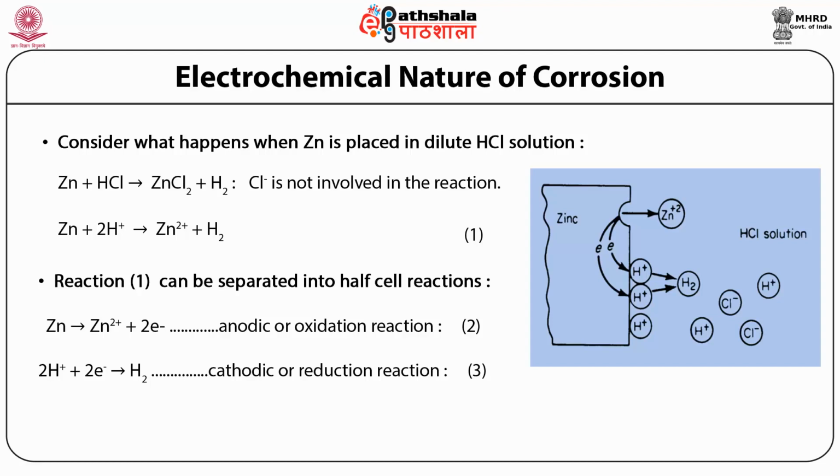If anywhere in a material an electron acceptance reaction takes place, there must be an electron loss reaction. The metal loses electrons and enters into the environment in ionic form. All the corrosion reactions, that is, material loss by electrochemical reactions, are oxidation reactions. Lastly, in the case of aqueous corrosion, the ions enter the corrosion product or the solution electrolyte.